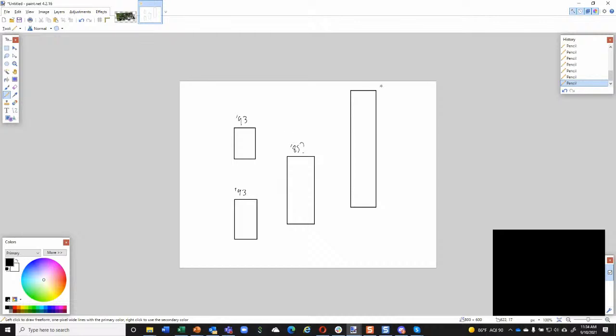And here's the 154. And the 85 you were saying is the magnitude comparator? Yeah, so you have A and B 4-bit inputs, and you have A greater than B, A equal to B, A less than B outputs, 3 pins. Yes, LS85. You nailed it.